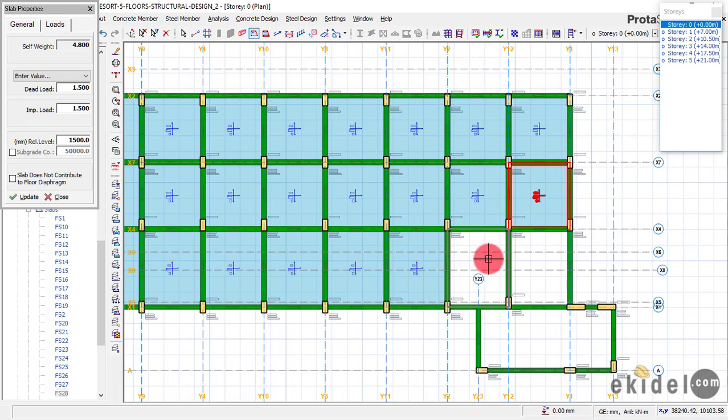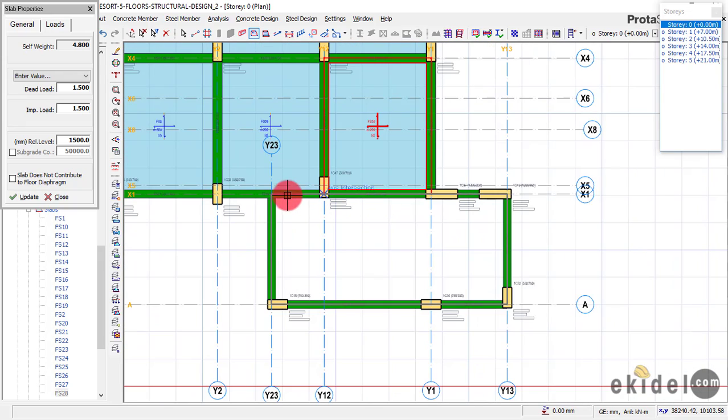That is from the Eurocode, and also from BS code, and also from US code, and also from British code and Indian code. Okay, so right now I want to insert my slab here, but this panel is very big, so I'll have to confirm if this panel is within that rule. When your panel gets bigger than that, you begin to have issues on your slab, on your Raft foundation, because that slab will tend to punch through because of how large the area is.